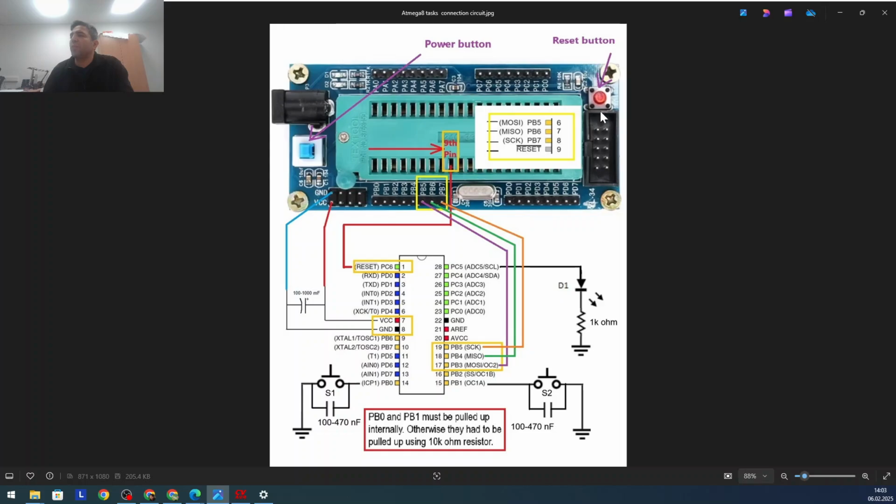So we will have this kind of layout that we have to connect with these programming wires. There are 6 wires. Those are programming wires, VCC and ground that we have to connect. Our Atmega 8 chip will be put on the breadboard, and you will connect those wires to the breadboard from this. So PB5, 6, 7 will be connected to PB3, 4, and 5 basically.